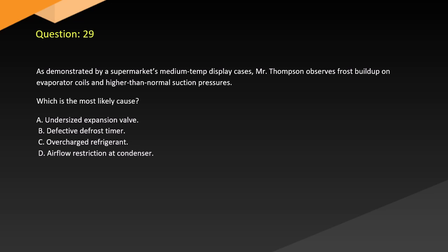Question 29. As demonstrated by a supermarket's medium temp display cases, Lopez observes frost buildup on evaporator coils and higher than normal suction pressures. Which is the most likely cause? A. Undersized expansion valve. B. Defective defrost timer. C. Overcharged refrigerant. D. Airflow restriction at condenser.